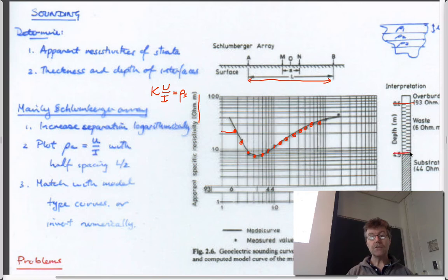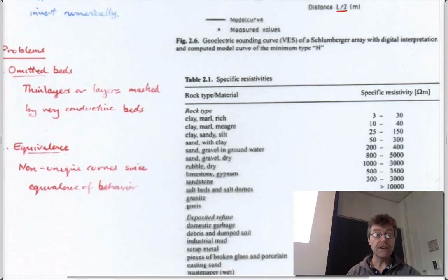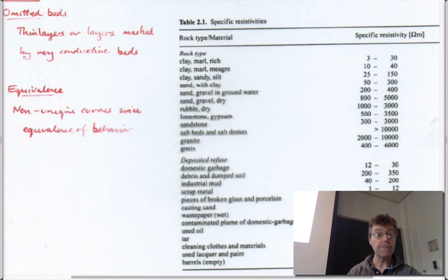geometry of the subsurface would be in terms of, in the upper surface here, a certain resistivity material, below it material with a different resistivity, below it material with an even different resistivity, and you use that information if you know what the resistivities of different materials are. I guess low resistivities for clays, higher resistivities for granular materials. So high resistivities would be low conductivities.